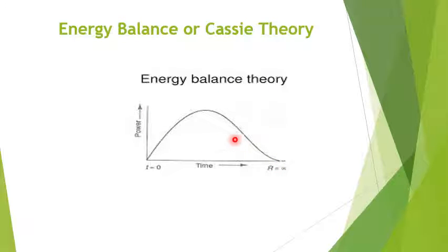Due to the rise of the restriking voltage and the associated current, energy is generated between the contacts, which forms heat. This generated heat has to be cooled as soon as possible by a blast of air or a flow of oil at high velocity and pressure.